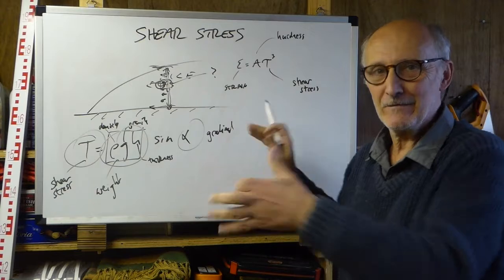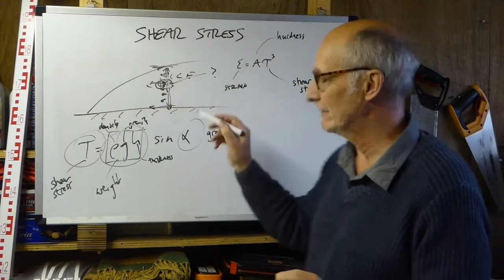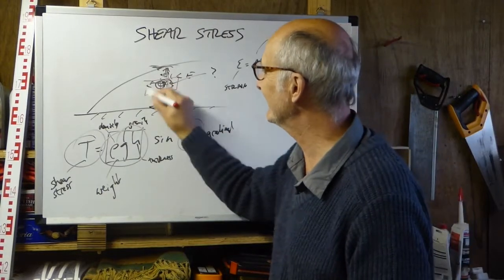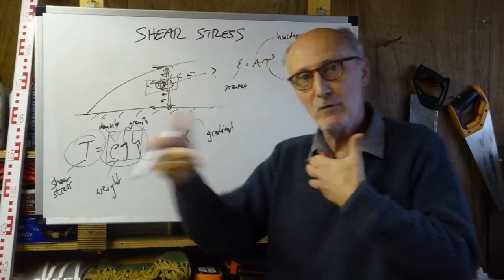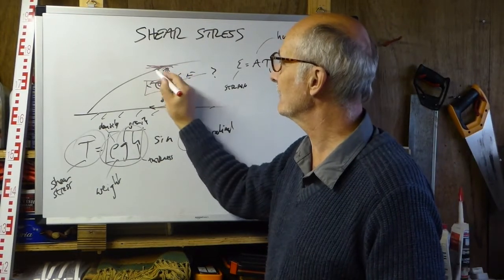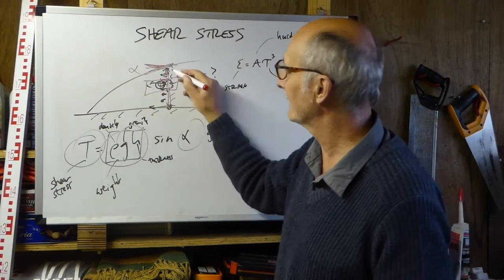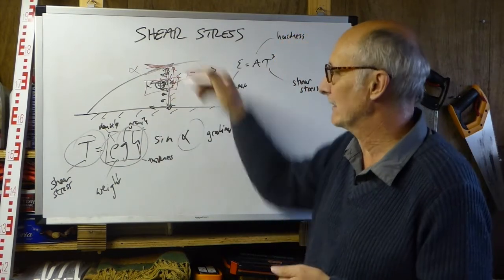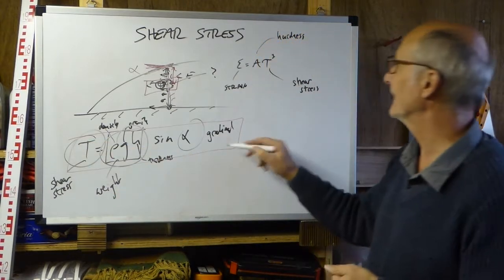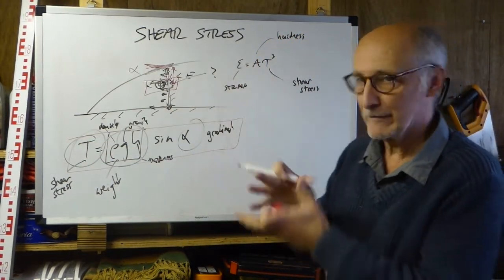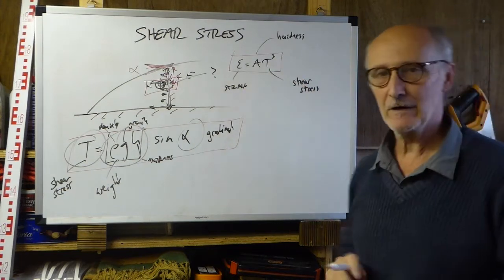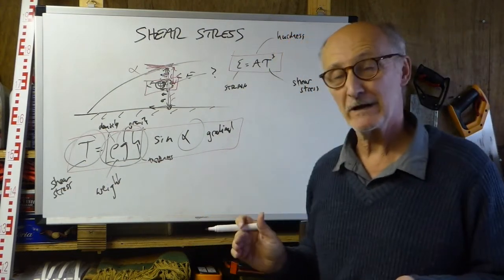Now, at first glance that seems very complicated and messy, but just pull it back to the very basics. All we've really got in there is we've said, well, to calculate the deformation, the creep, the movement within the ice at different levels through an ice sheet, all you need to know is the surface gradient there and the thickness of ice or the weight of ice bearing down on the point that you're interested in. So tau is given by rho g h sine alpha, and then you can calculate E, the strain or the deformation, because the strain is a function of the stress, making allowance for hardness or temperature. So it's a very straightforward kind of relationship.